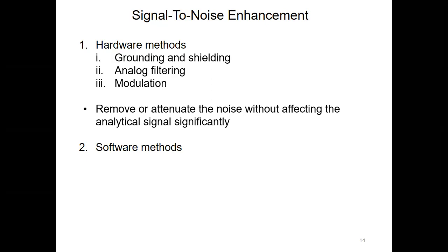You will see sometimes when we use a software method, it will cause certain alterations in the signal. But when we do hardware methods, the signal does not change significantly. Without changing the signal significantly, it will either remove or attenuate the noise. We cannot say it completely gets rid of the noise all the time, but it will either attenuate or remove the noise.